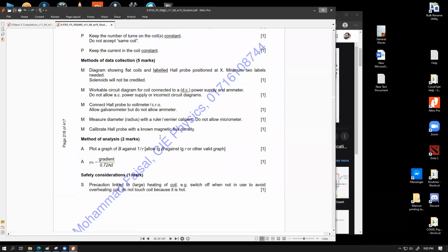What this essentially would mean is that you have to have the Hall probe, and you have to have a source of magnetic flux density available in your lab, or from your teacher, that the teacher knows. You'd have to calibrate that Hall probe with that fixed magnetic flux density value, so that you can use a proportionality relationship to convert those individual voltage measurements out of the Hall probe into relevant magnetic flux density values.